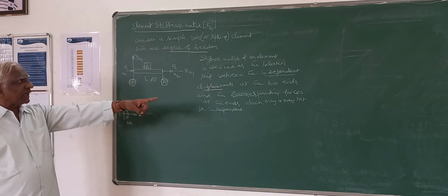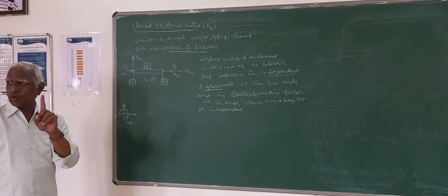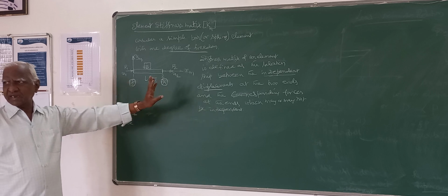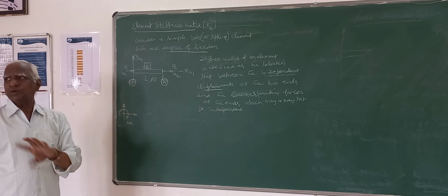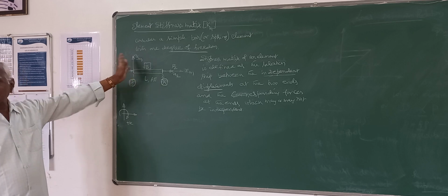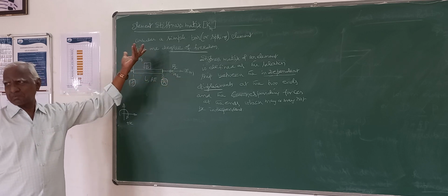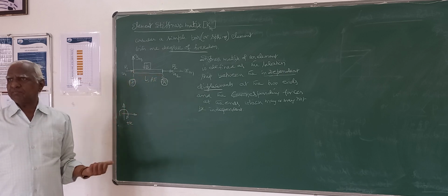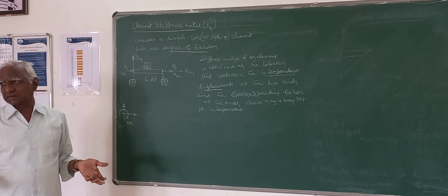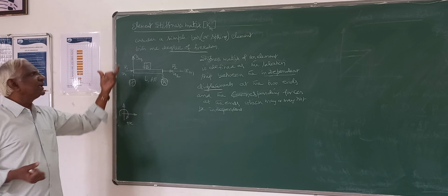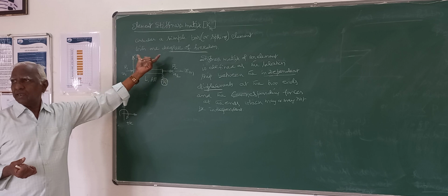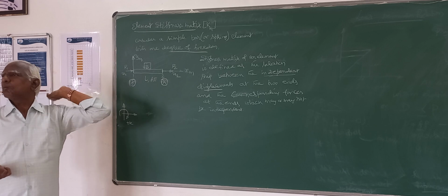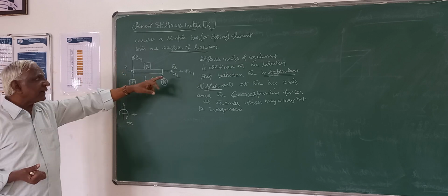Of course, stiffness pertains to one quantity, one force and one displacement. I have already defined stiffness as the force required for unit displacement. But here I am considering a system of forces and displacements. The moment I consider a line element, it always has 2 ends. At the 2 ends we consider the possible forces and displacements. Here I am considering the case of only a bar element, wherein there is only one force resulting in one displacement at one end.